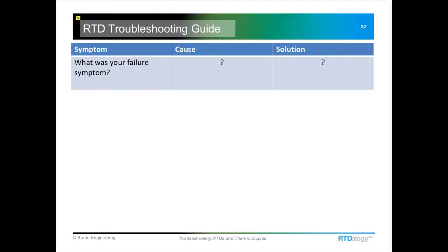It could be something as simple as someone turning on a light switch somewhere and that shoots power into that grounding. And probably the first thing I'd try here would be to somehow better isolate the thermocouple and the readout equipment from the rest of the electrical system within the building.